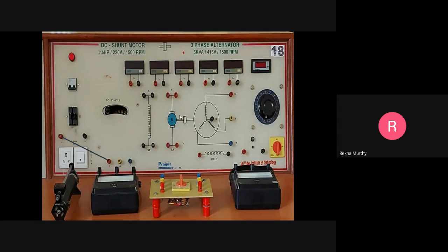So this is for the connection as usual. The positive is connected to the line, and the rheostat is connected to the field, and the other end of the rheostat should be connected to Z, and ZZ coming back to the negative supply. So this completes one closed loop of a part of the field winding and the line. Next, coming to the armature side, the armature terminal should be connected to the motor, and the other end of this, AA, should be connected back to the negative supply or to ZZ. So this completes your DC shunt motor connection.